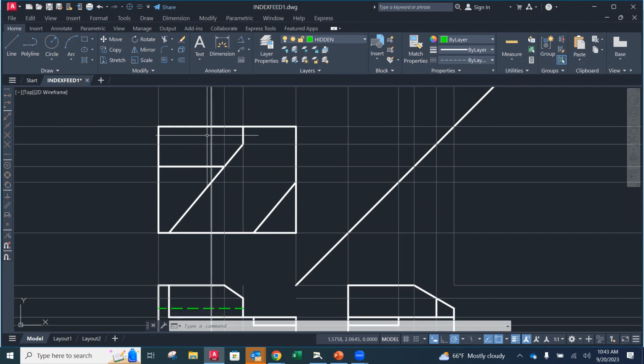I'm going to do a snap from this corner, and I'm going to put the coordinates in and up. That way I don't have to do an offset of anything, because I don't have this location right now. So half of 3.25, is it 1.625?